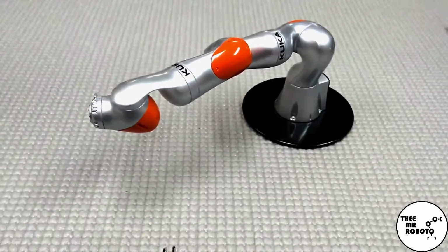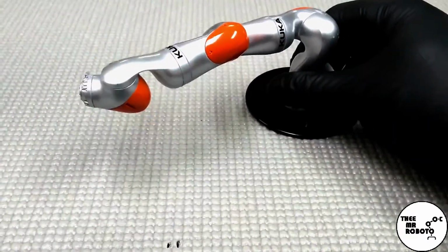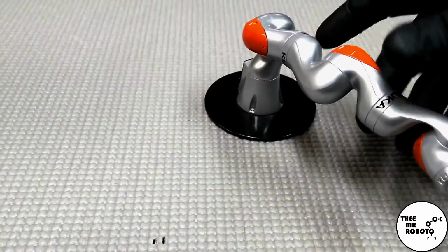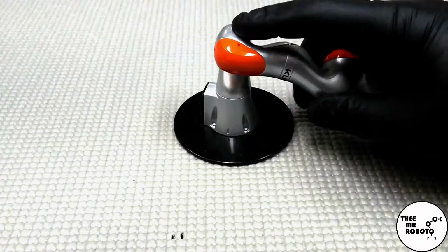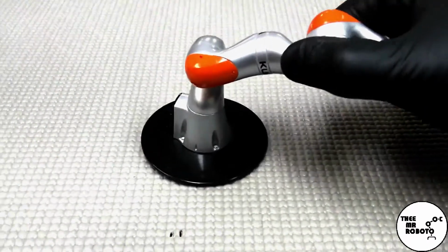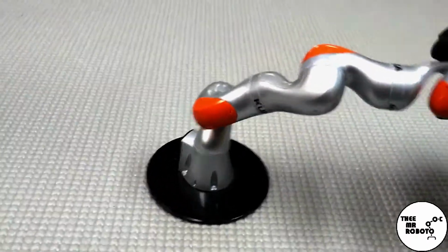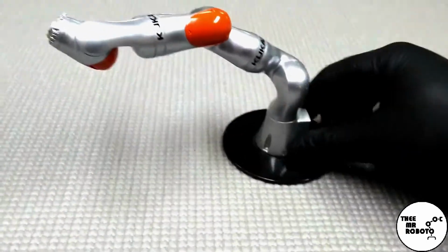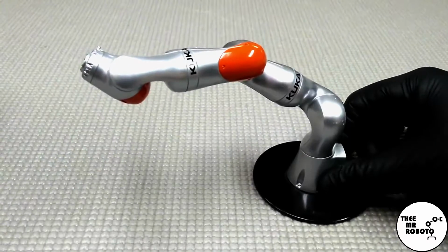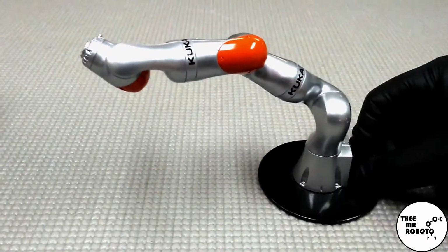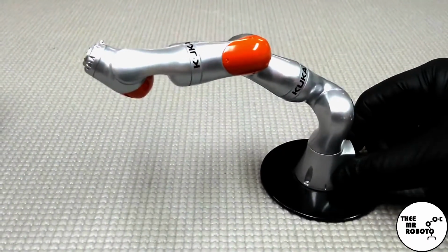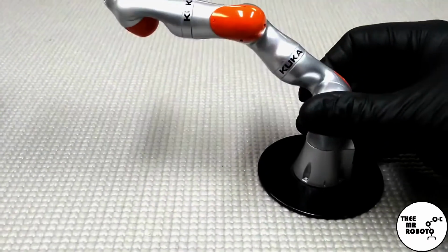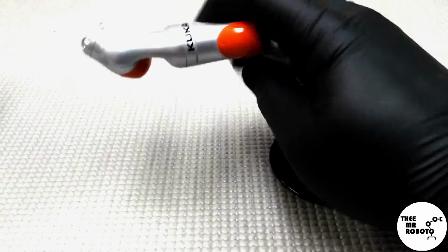Okay. The other way to program is you do have the option to program based on the angle of each individual joint. Okay, but when you look at that position in your robot controller, it's not really going to help you out that much. It's not going to do you much good because it's just going to show you a bunch of joint angles, right?